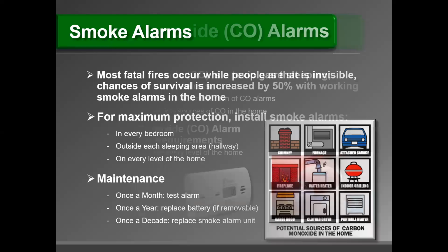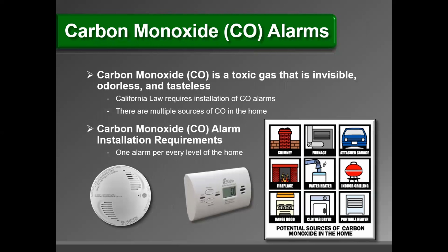Next slide. We'll talk a little bit about carbon monoxide in this one. Like I said already, carbon monoxide is one of the components of the gases from combustion in a fire. It's now required by law to have a carbon monoxide monitor. These can be plugged in or hardwired. Carbon monoxide is about the same weight as air, so it mixes readily. So they can be plugged in low in an outlet, but you should have it away from the heater where the heater blows out. You want to have it a few feet away from that at least.